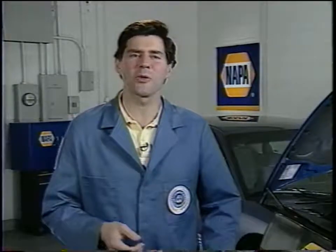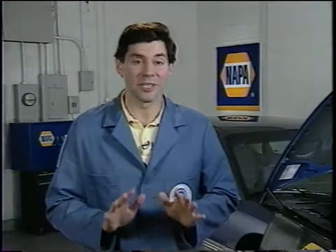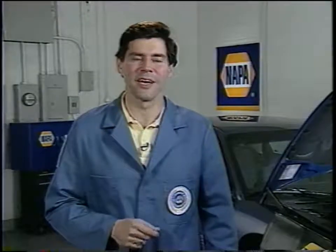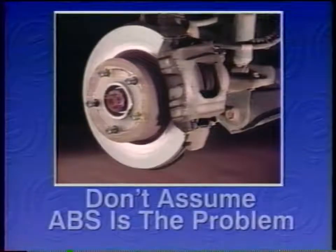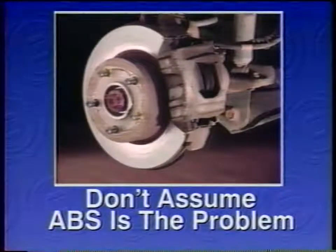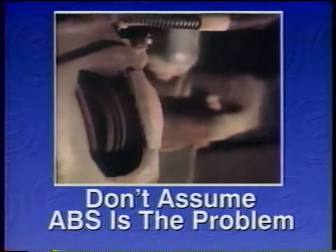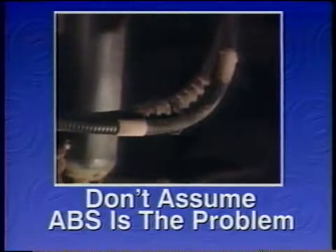Diagnosing and troubleshooting anti-lock brake systems can be a rather intimidating process, but it doesn't have to be, as long as you keep a few of the basics in mind. The most important of which is don't assume ABS is the problem. The majority of customer complaints on ABS-equipped vehicles will stem from conditions in the conventional part of the system.